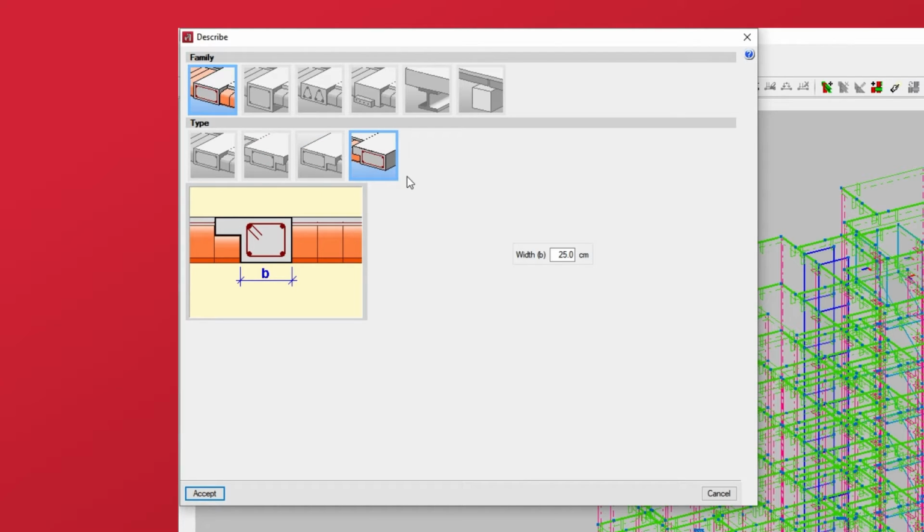Flat beams adopt the value of the depth of the adjacent floor slabs, which can be defined from the Edit Beams option. Therefore, in this section, the program only requests the width. If the beam is located between two floor slabs with different depths, it will assume the greater of the two. If it is located between two floors at different levels, the depth of the beam will be increased to reduce the difference in level.